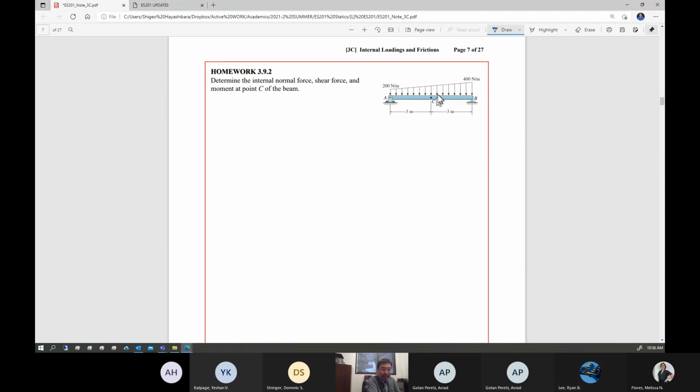You would say no? Probably, because of the different pressures, is that why? This is a distributed loading, which keeps increasing and increasing, and that is going to affect the shear big time. So this is probably not the maximum point of the shear. As you design your beam, you have to design based on the critical location.